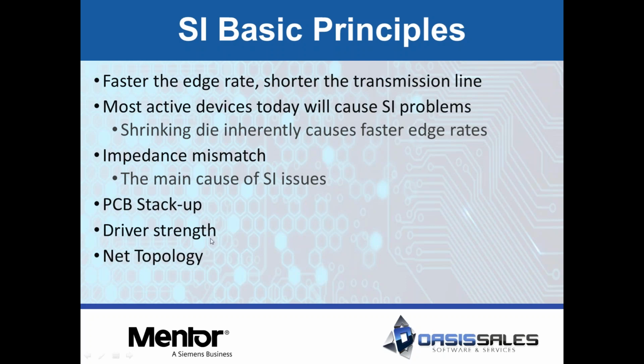Driver strength is another cause of signal integrity issues. I mentioned that already in the first point, that a lot of these chips you're using nowadays, you control the output drive current, but a lot of simple logic devices may just be stuck at 12 milliamp drivers or 8 milliamp drivers, which are actually pretty strong nowadays, especially when you're in the 3.3 volt and 1.8 volt range.